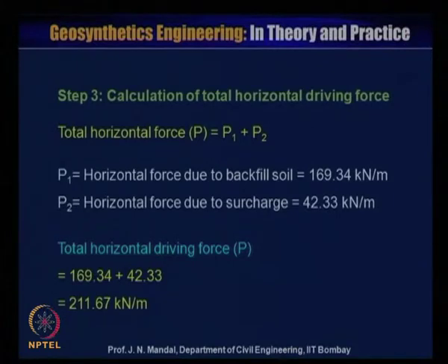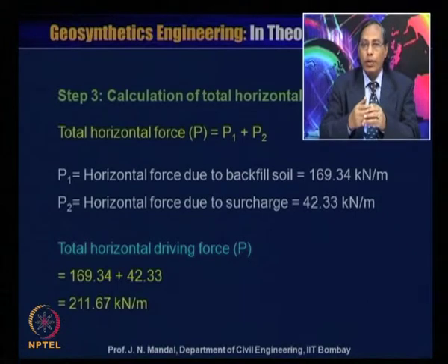Step 3, we can calculate the total horizontal driving force. The total horizontal force P will be equal to P1 plus P2. P1, the horizontal force due to backfill soil, is calculated as 169.34 kilonewton per meter, and P2, the horizontal force due to surcharge, is 42.33 kilonewton per meter. So the total horizontal driving force P is equal to 169.34 plus 42.33, which is 211.67 kilonewton per meter.